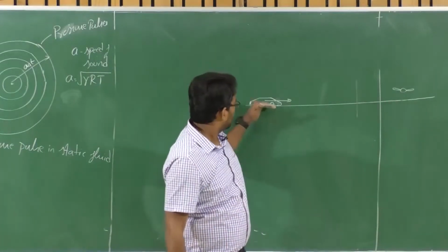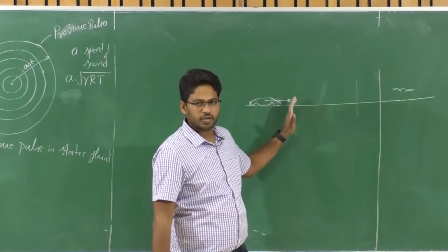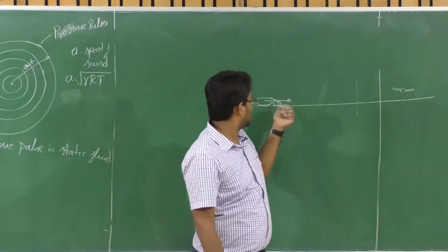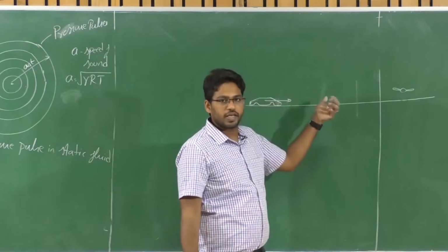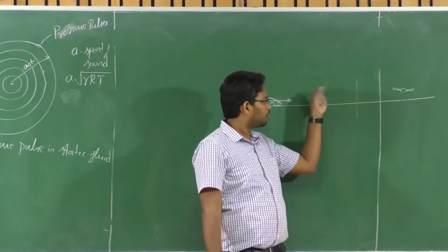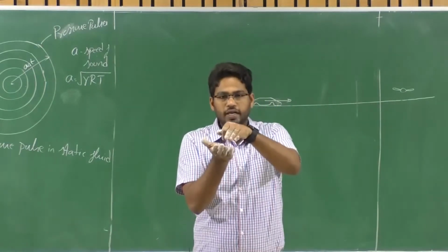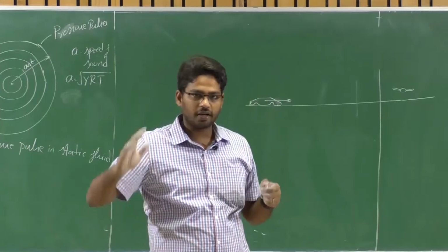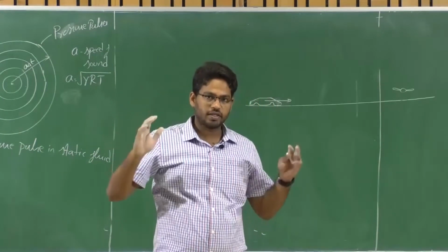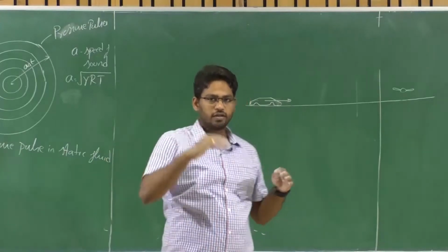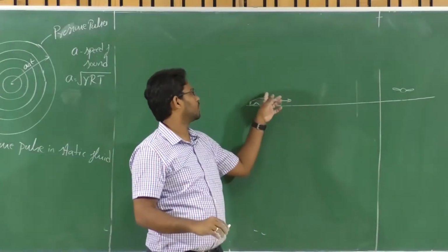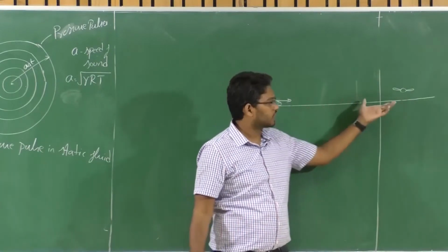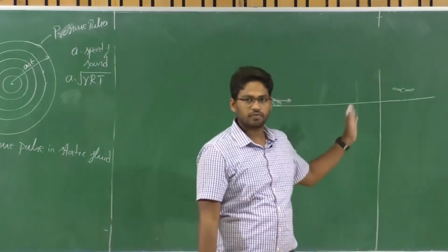That happens because when you're traveling, the disturbance that you're creating is also moving ahead, right? It is not that it is just moving back. It is also moving ahead, and it is moving in all the directions. The flow particles ahead of the vehicle will try to adjust accordingly. They will try to figure out where the disturbance is minimal, right? And the fluid particles in the form of these streamlines can bend across this vehicle so that they can smoothly flow over this particular body. Fine. So this is true as long as the disturbance is traveling forward.